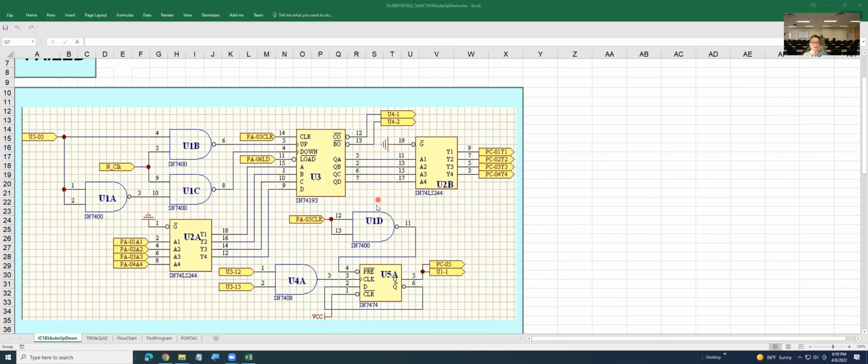Now, if you're looking at this circuitry here, I want to clear. Then PA5 has to be logic 1. Correct? Correct. For clear. Okay. PA5 at a logic 1 and this also at a logic 1, one in the input of the NAND and the output will be 0.